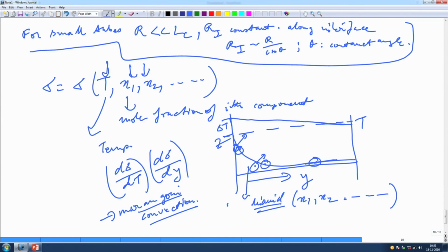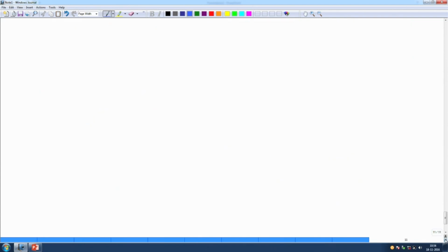So, what have we done? We have determined the shape of the interface, we have understood what the interface should look like, right. We have established the Young-Laplace equation and we know how the molecules behave inside the liquid and close to the interface. Now, we will introduce the problem here and complete it in the next lecture, that is, wetting and contact angle. This is a very standardized problem that we need to understand, and we will do Marangoni and all these other flows in here.